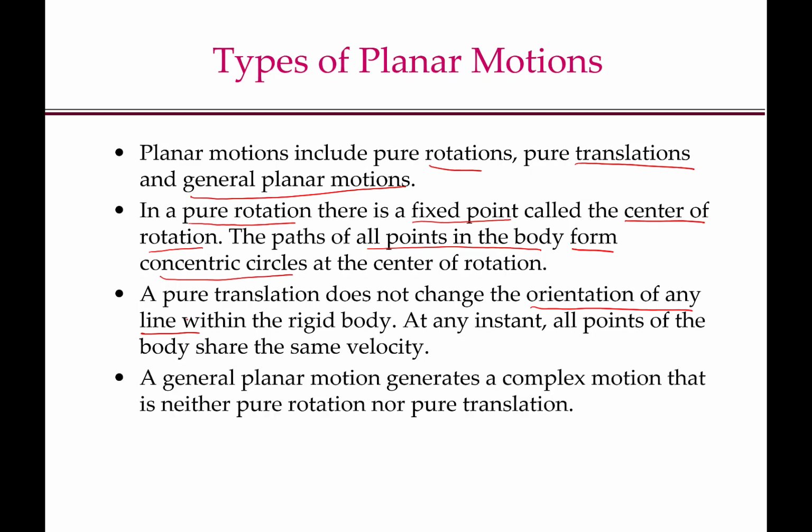A general planar motion is a complex motion that consists of both rotation and translation. However, as you have studied earlier, any general planar motion can be thought of instantaneously as a pure rotation about an instantaneous center of rotation. The difference between pure rotation and general planar motion is that the instantaneous center of rotation is always constant in pure rotation. It does not change with time. Whereas in general planar motion, the instantaneous center of rotation is changing with time.